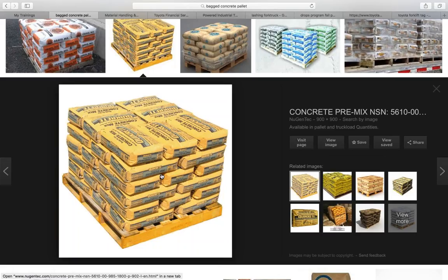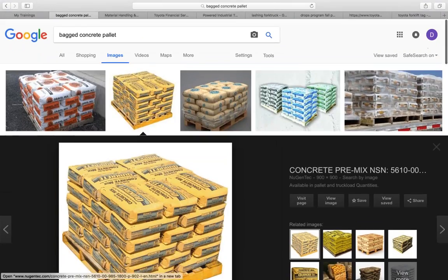Also using debris nets, catch platforms, canopies if possible, using safety glasses, all of our PPE, right? Glasses, shields around any types of machines, anything where there could be projectile hazards, inspecting tools to make sure that all the protective guards are in good place, making sure that we're trained to properly operate any powder actuated tools. We talked about that last week.